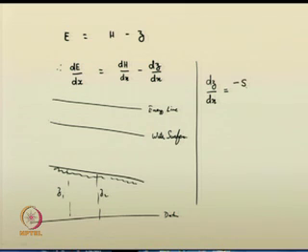So, we have already discussed this thing. It is the negative, minus S0. We have to give it minus S0 because the datum head is decreasing in the flow direction. dH by dx, this is your energy slope, that can also be given here as SE or SF. If you recall, we have approximated energy slope with the friction slope. So, it is SF.